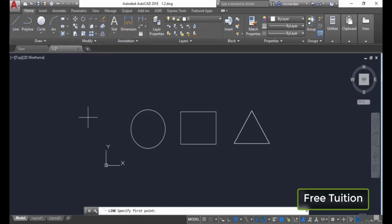Simply go to that command and left click, and the command will now be activated. Once the command is active, you'll notice that its name and also the instruction will be visible on the command line, and the cursor will change into this point selection cursor or into a pick box. In order to exit this, simply press the escape key. You can press escape multiple times also if you want, so that will not make any change to the drawing.